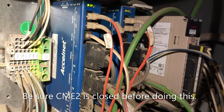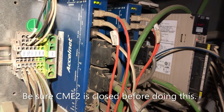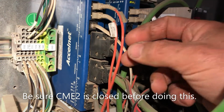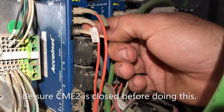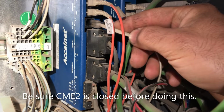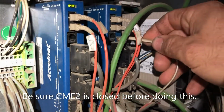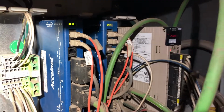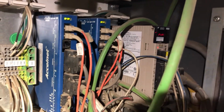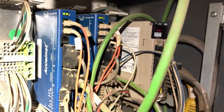The way that you check the fault codes from one amplifier to the other is this cable right here. Communication cable. It's just like a little phone jack cable. You remove it and you can install it in the other amplifier. And then we'll go back to CME2 and we'll check the faults on that amplifier.